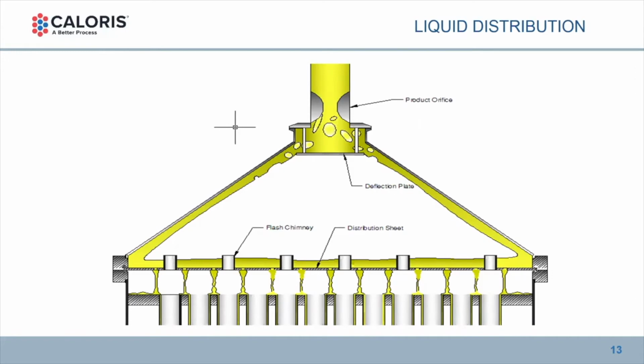So a lot of engineering goes into proper design of a distribution plate here. And that's not even to mention making sure those holes line up properly. They've got to be matched properly to distribute liquid all around to all of those tubes, so it falls on the meat of the tube sheet plate. You certainly don't want that liquid falling down the center of a tube, because there's no heat transfer taking place then. It's just free fall of liquid through a tube.